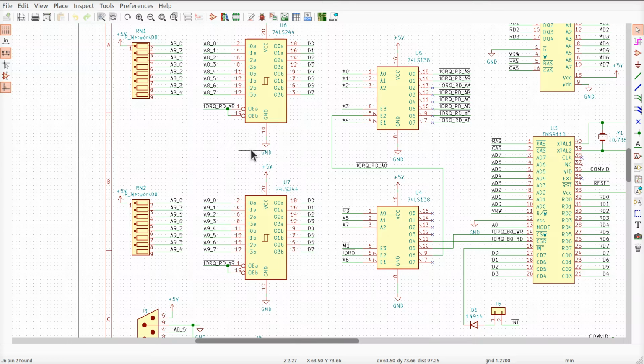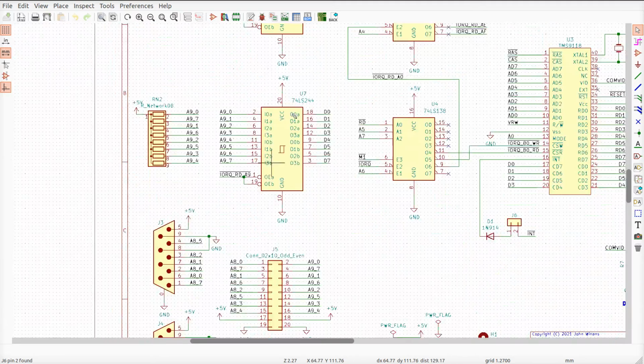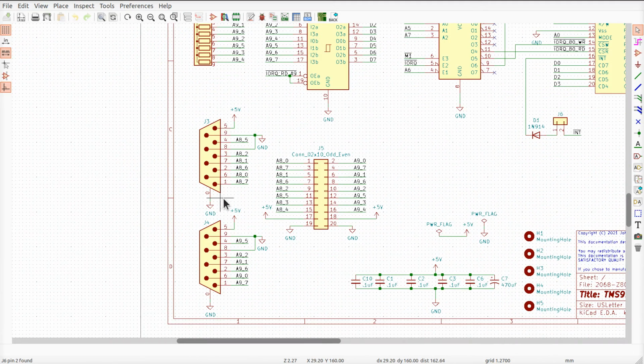Okay, I found some old joysticks lying around that are Atari compatible, which means they have a DB9 connector on them. And if you're young, you might think of the DB9 as a COM port or an old COM port, like on your PC, or the RS-232 ports on the Retro board with the ribbon cable that I made that has a DB9 on it for RS-232, right? Well, the Atari joysticks use the same connector.